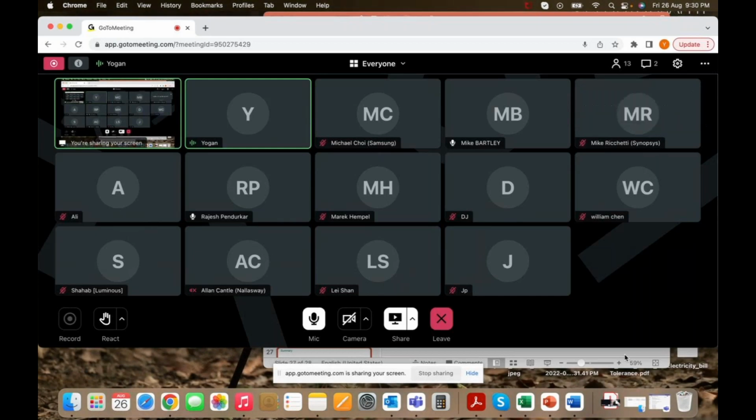But if you put it into the bigger package and there is some memory failure for various reasons, you still need the ability to go inside and repair, and bring in spare memory lines, address and data lines, so that you don't waste the die. So it is not just for testing the die alone. There should still be spares available after it is integrated into a 3D package so that you can still correct to some extent. Thank you.